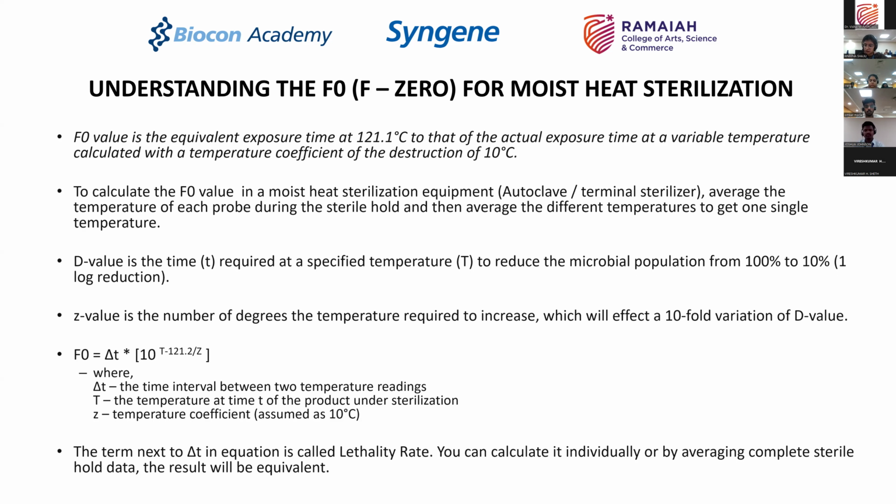Whatever the case, I will feed that value, based on a known flora, into the autoclave program and say I am fixing the Z value. Now at an interval of 5 minutes each, measuring the actual temperature inside the autoclave, tell me what is my F0 value.